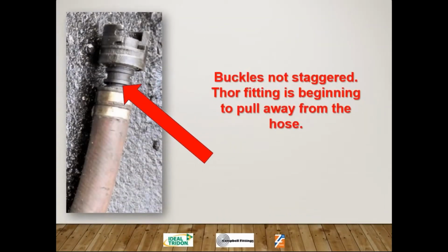This shows you a Thor fitting. The buckles are not staggered, and it's beginning to pull out of the hose. So you're not really getting the hose retention that you need here. And that fitting kind of looks a little on the rusty side too.